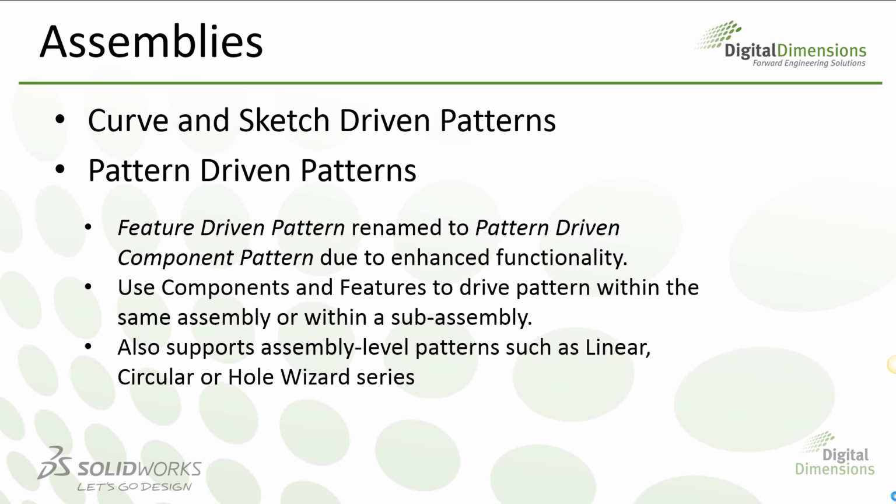The next new feature is some changes to the way that patterns behave within assemblies. We now have curve and sketch-driven patterns, as well as a change to the feature-driven pattern. The feature-driven pattern has been renamed to pattern-driven component pattern due to enhanced functionality. We can now use components and features to drive pattern features within the same assembly or within a subassembly. This also supports assembly-level patterns such as linear pattern, circular pattern, or Hole Wizard series.